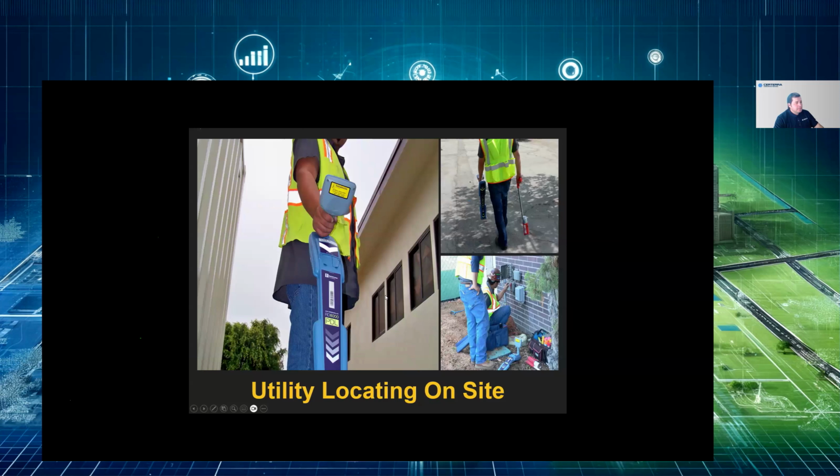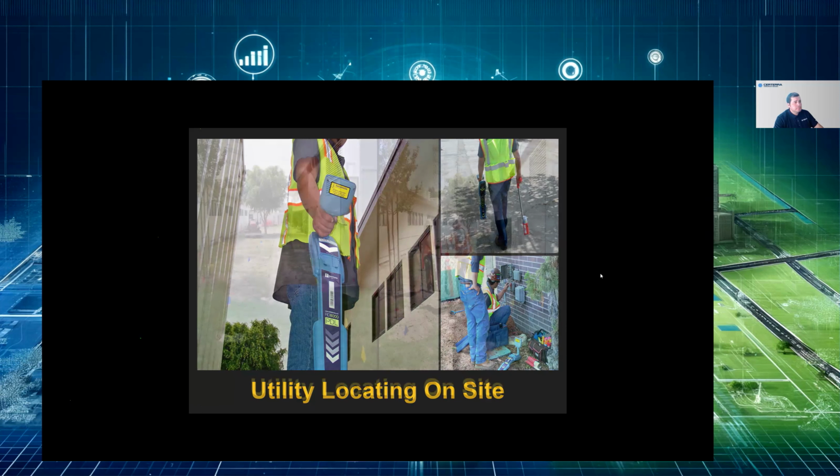Here is the technician doing the sweep. Here, the guys are connecting the base to maybe a cable or communication lines, so they can trace the electromagnetic signal afterwards. Once they find it after they sweep in here, they go ahead and put paint to locate where they found the signal.